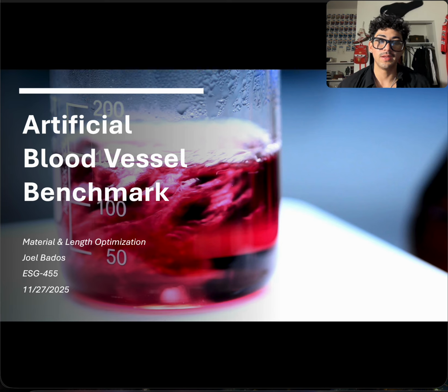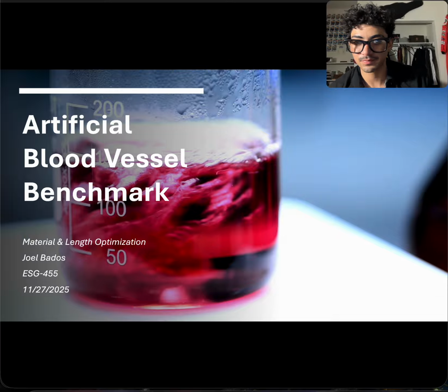Hello, I'm Joe Vados. This video presents my artificial blood vessel benchmark project for an executive manufacturing audience. I use SolidWorks flow simulations to compare three common graft polymers, which include PTFE, PET, and polyurethane, and I test them across three graft lengths and two different flow conditions. The goal of this project was to translate simulation outcomes into a clear manufacturable product recommendation.